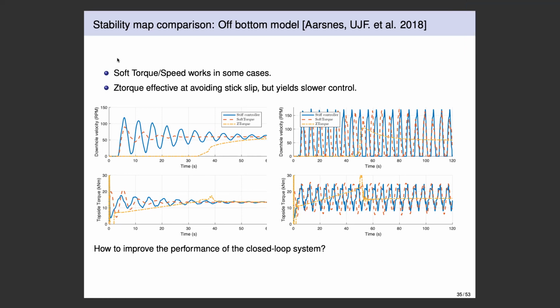No, and admittedly, now you've got so many parameters in your model that you can make it fit anything. The reality is, can you measure what's important or not? Right, exactly. I'm talking about drilling experience: it seems there are two things. I can be drilling, everything is fine, and then I go into a more difficult section of drilling, which can be the drill bit, but then it can even be off bottom. I've attributed it, like Roman said, to the anhydrites and even some of the limestones that'll be more difficult in terms of stick slip than a shale or something like that, perhaps.